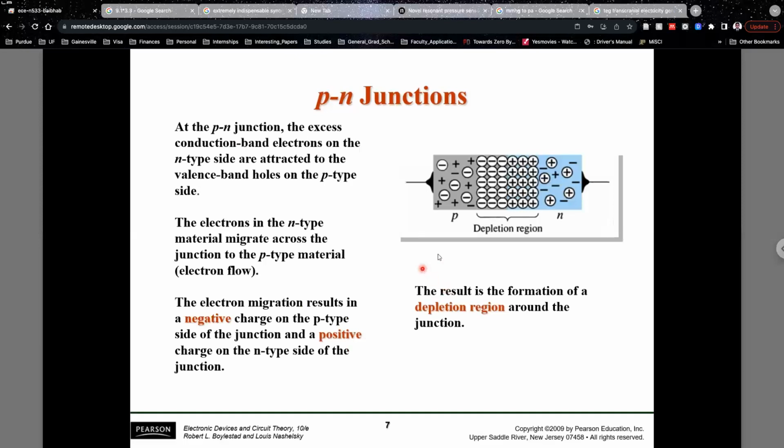You know that the p-type semiconductor will have an abundance of holes. Remember that the example shown on the board right now is n-type, because you have a phosphorus which has an additional conduction band electron. So it has an additional dangling bond, or an additional electron, that can flow through this entire structure. That's the example you see on the right hand side, where the excess electrons are shown.